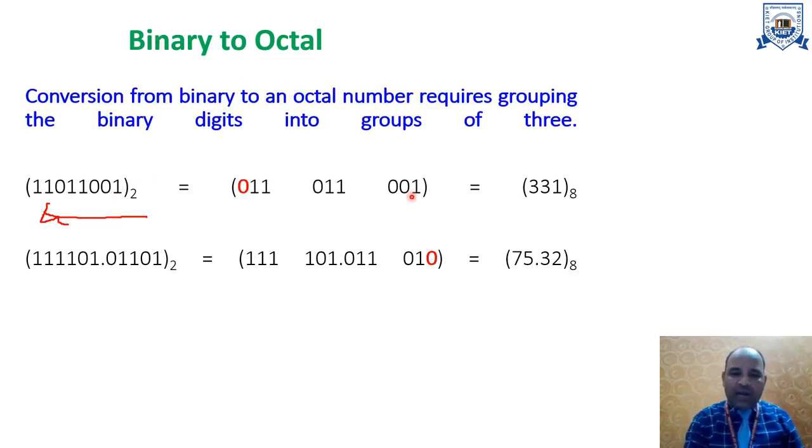And now friends, we can find the equivalent straight binary value. Make sure that in other number systems, like BCD numbers or excess-3 code, they also use the digits 0 and 1, but BCD numbers are different, and gray code numbers are different. When I say binary, this is called straight binary. So when you have grouped into groups of three digits, you write the straight binary equivalent of each.